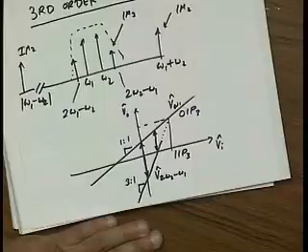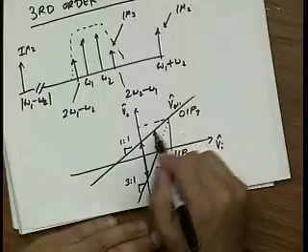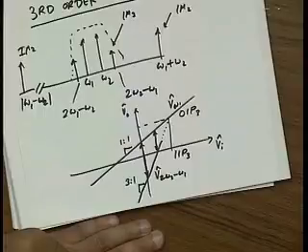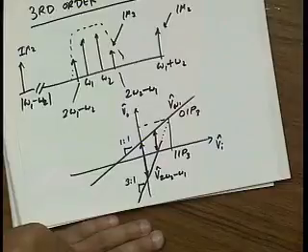By twice, right? So 20 dB. So if I want 100 dB IM3, I have to back off 50 dB from the IP3 point. So operating at minus 50 dBm would give me 100 dB theoretically of IM3. Okay? Questions?